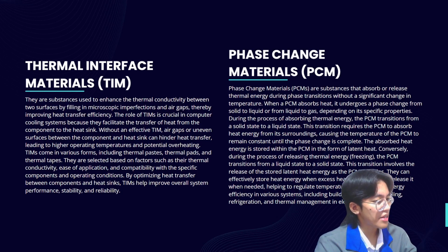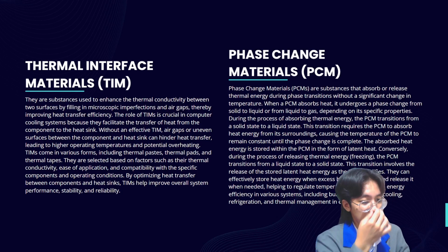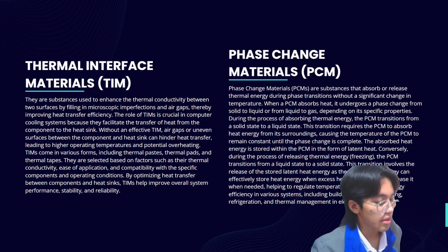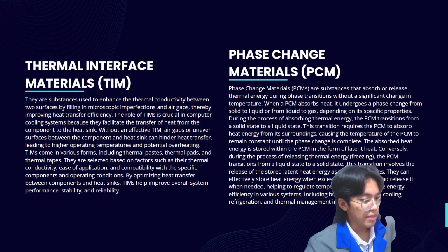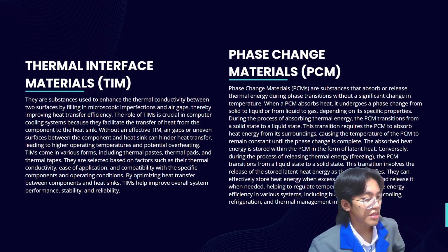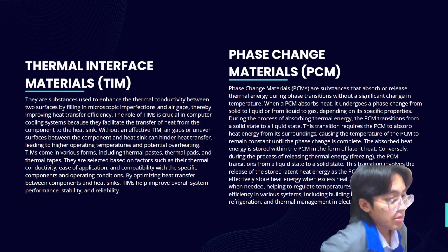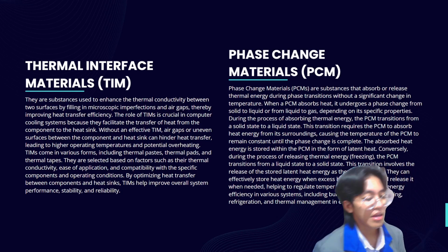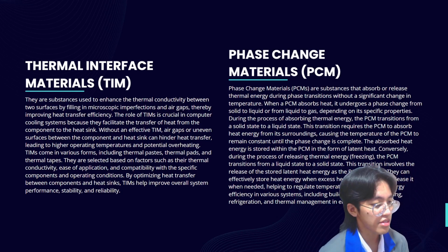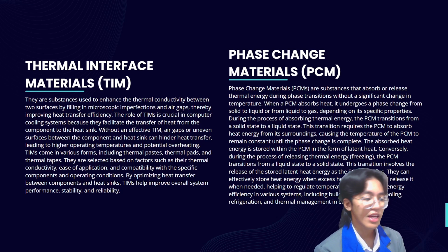TIMs come in various forms including thermal paste, thermal pads, and thermal tapes. They are selected based on factors such as their thermal conductivity, ease of application, and compatibility with the specific components and operating conditions. By optimizing heat transfer between components and heat sinks, TIMs help improve overall system performance, stability, and reliability.